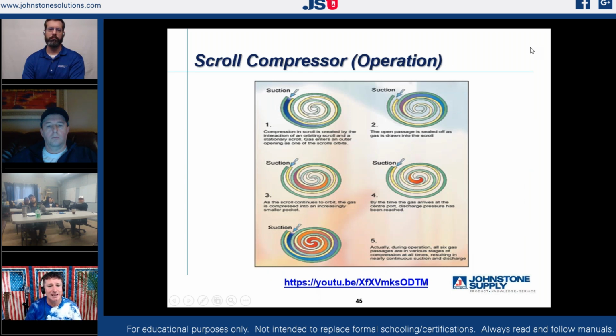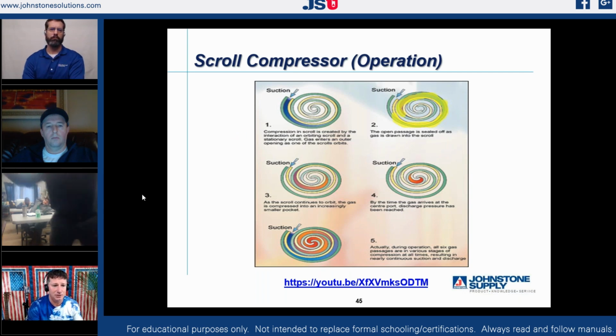Maybe. So inside of that vapor pump, here's what we're actually doing. We have multiple compression processes going on all at one time. So our actual entire scroll maintains a fairly evenly distributed pressure along its entire surface. And how we are doing that is in that multiple compression stroke. So we're going to bring in our vapor, right? We're going to bring suction into this portion of our scroll plate. So a large opening at the entrance, and it diminishes as it gets to the end of it. As we rotate inside that motion, we're now going to close off that part, and we're going to push our vapor further inside of that rotational cycle.